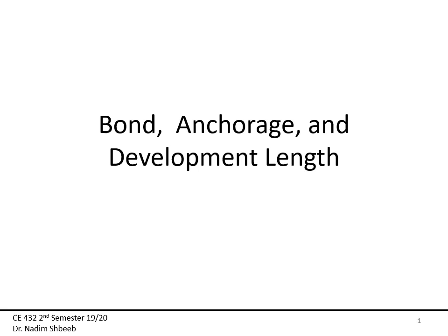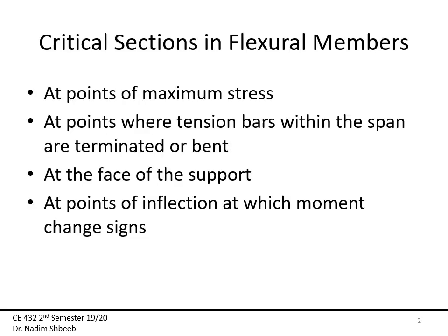So at maximum moment, maybe I have 5 number 25 bars, for instance. I don't need the 5 bars obviously for the whole beam. I only require maybe 2 or 3 of them at certain sections with lower moments. So here I'm going to show you how we are going to do that.